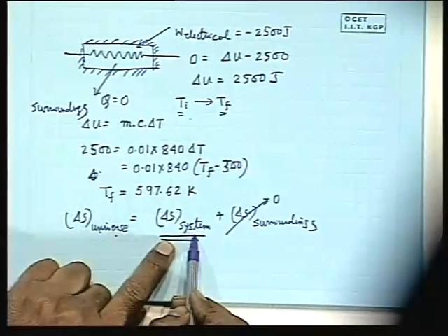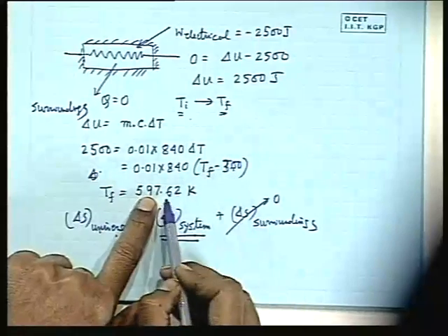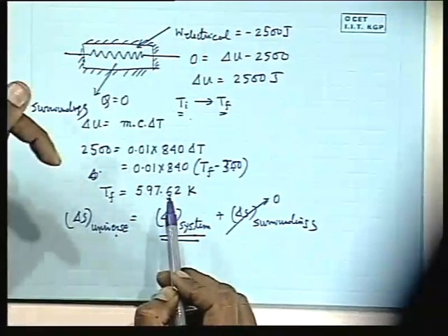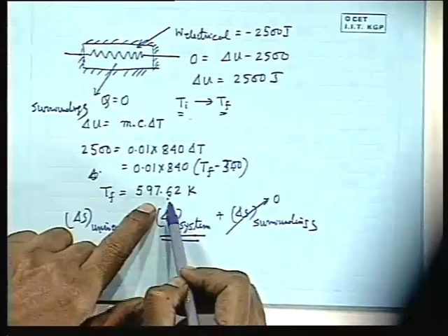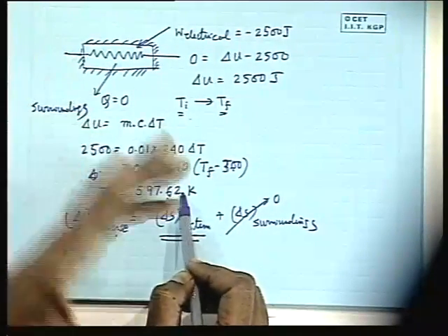So system entropy changes because of the change in its state, which is manifested through this change in temperature from 300 K to this, which could have been possible by a reversible heat transfer. But because it is an irreversible process, the temperature change is possible even without heat transfer. But in a reversible process, temperature change is never possible without a heat transfer. Only in an isentropic process, temperature change is possible without heat transfer, only by expansion and compression, that is a reversible adiabatic process. That will be made clear afterwards. So therefore this is enough.